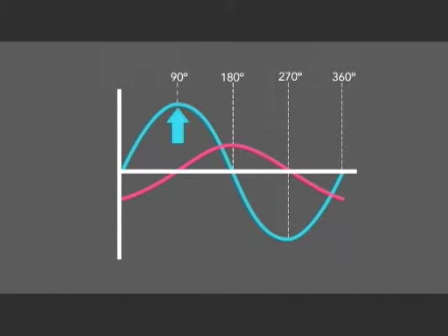When the voltage is at 90 degrees, the current phase curve is at 0. This current cycle is always 90 degrees behind its corresponding voltage. This current is inductive or non-working current. Let's go back to our illustration where the current and voltage are in phase.